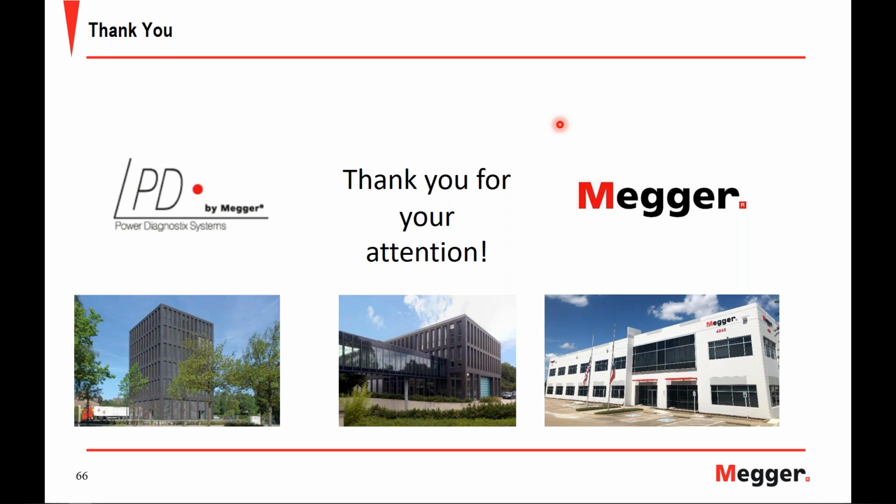All right, thank you. Charles, is there any additional benefit to the tan delta over offline partial discharge testing? There's a benefit to performing both of them. I don't think there's a benefit to performing tan delta over partial discharge, because tan delta or power factor measurements are going to give you, as I said before, an averaged condition assessment of your insulation.